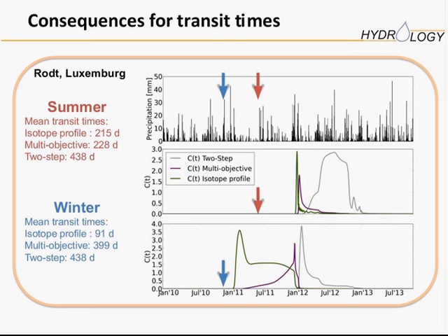Do you notice any equilibration time differences in dry soils versus wet soils when you're doing that sampling? No, not much. We didn't go to 5%. We looked at what we can usually expect in the soils, somewhere between permanent wilting point, field capacity and saturation, and there we couldn't see much effect because the porous membranes we use have a relatively high throughput in vapor.